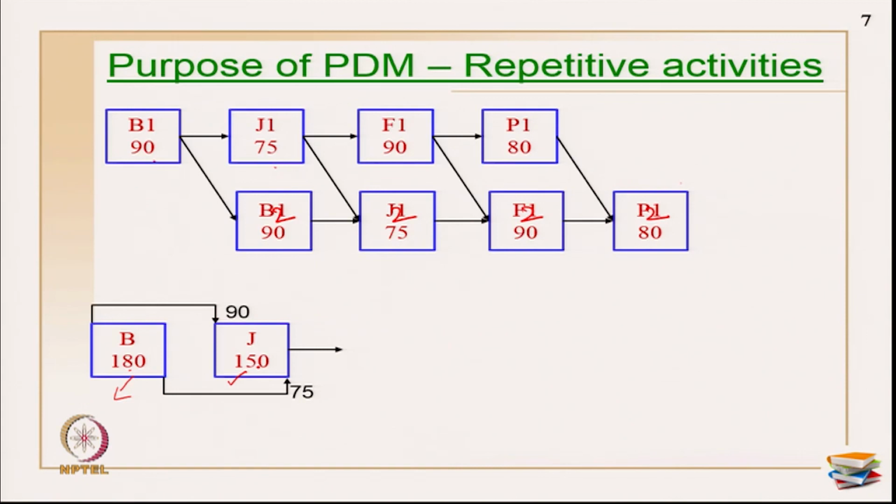So how do I now fix the relationships? So all these relationships I have, how do I fix it? So what I am going to do is, after the brickwork started, 90 days after the brickwork, joinery should start. So this will cover my brickwork. After the brickwork, this logic is primarily covered. After the brickwork, 90 days later, brickwork takes generally 90 days, then the joinery starts, and this duration is given here with the lag. Okay.